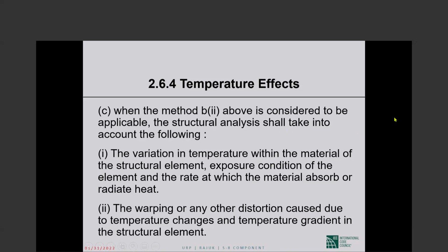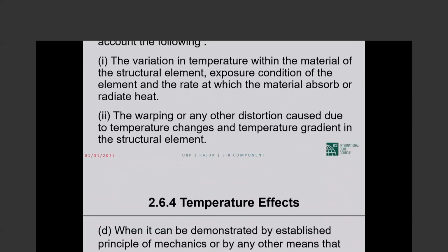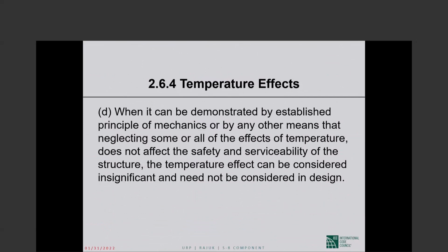Okay. And my advice would be, if you have to deal with these temperature effects, really deal with them. Look at the PCI design handbook, and it may give you ideas. This kind of analysis is very difficult, and I don't even have a good reference for you. I'm sorry to be that negative, but that's the situation. This is my experience. It's very tough to satisfactorily figure out the effects of temperature by analytical means.